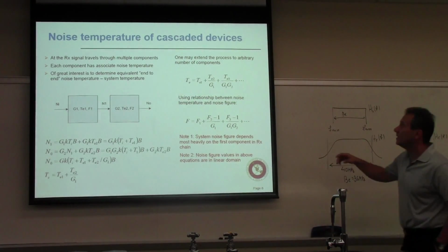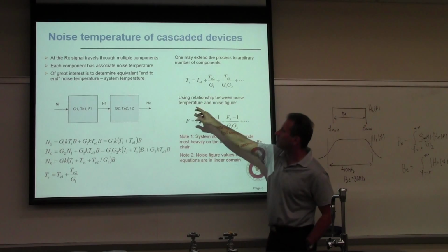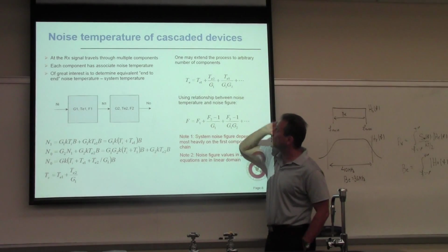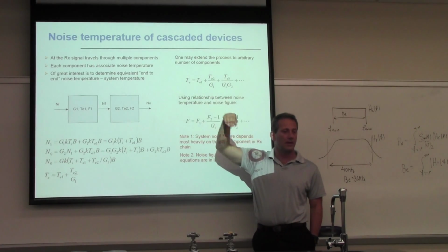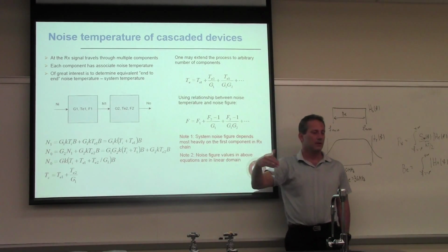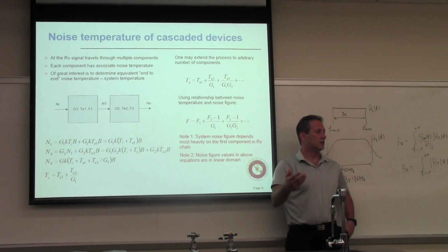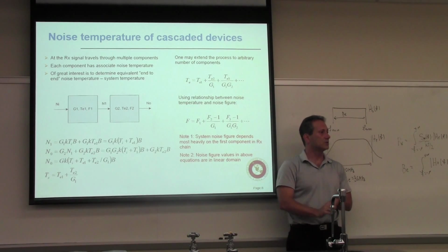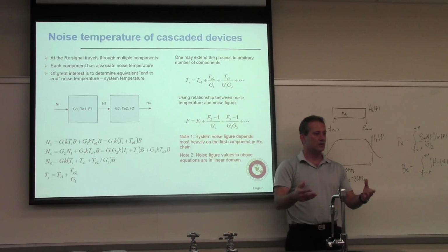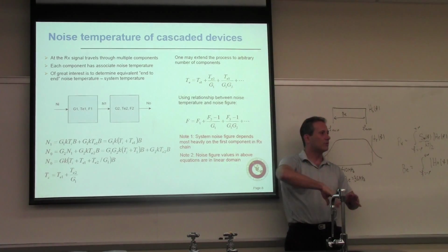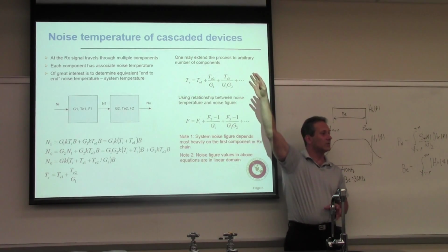Correct. So usually here's how it happens. After the waveguide, which is treated separately, I'll show you how you do it, you have an LNA. The LNA has a large gain, but then what you have after the LNA is a mixer. Mixer is what brings the signal down to the intermediate frequency where you do all the processing. And the mixer, by its very nature, is a non-linear device. If you remember, it multiplies by a sinusoid, so you get energy at double frequency and the lower frequency, and you filter out whatever is at the double frequency.